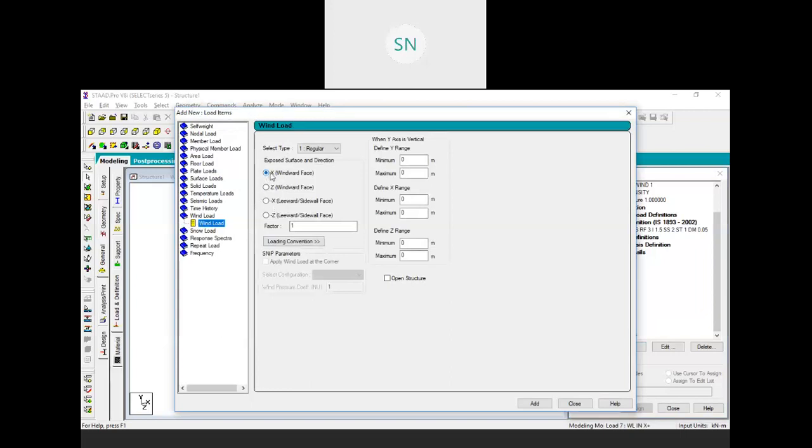So click on the x, and type your wind factor over here. Let me take our factor 0.8, because 20% air is going to escape, right? So only 80% air is creating pressure on my model. But we have 2 things over here, windward and leeward. So what is this windward and leeward?